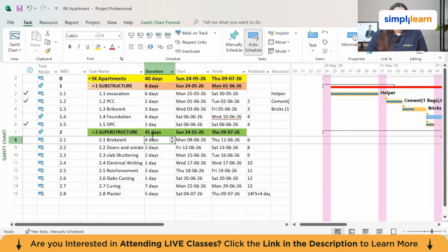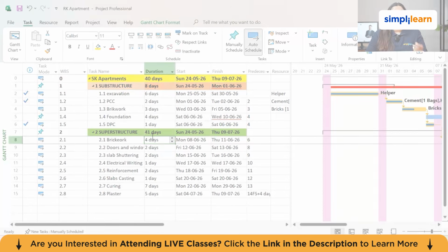The Gantt chart print, done properly, is still a standard deliverable for construction program submissions. Clients, employers, and regulatory authorities expect a printed Gantt chart. MS Project can provide a submission quality output if you control the time scale, the data, the header and the footer, and the page setup. Take the time, set this up correctly at the start of your project, and then save it in the view. Every subsequent print will be consistent and professional.